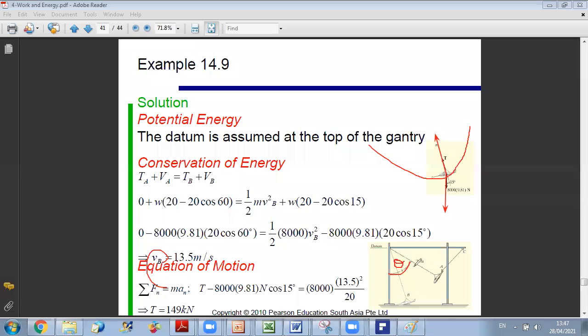So we will now take any position theta. For this position, we have the force T along UN. UN is towards the center of rotation, which is this point. UT is tangent to the path, perpendicular to UN. And we have the weight force. This is the weight force. The weight force is making an angle with UN. If you do the projection, if you do the elongation of UN, this angle here between the weight and UN is equal to theta.